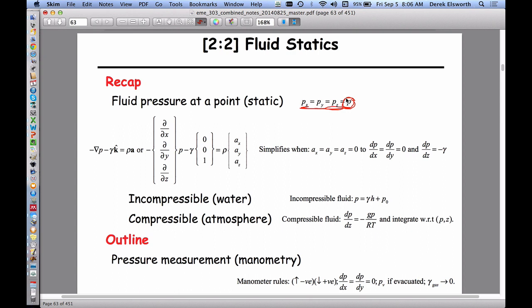If we look at fluids which are static but are accelerated, we end up with a number of relationships by resolving in the different orthogonal directions, z vertically upwards, x and y horizontally in the horizontal plane. And as a result of that, we get a number of simple relationships which we can write in this form, or in this form here.